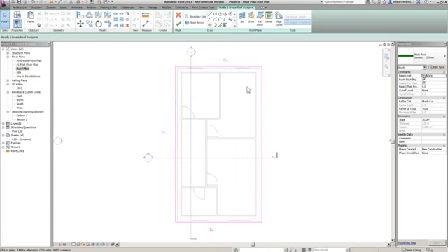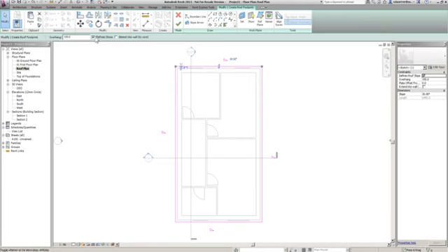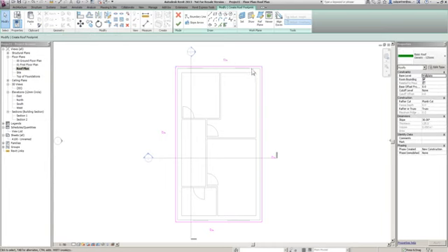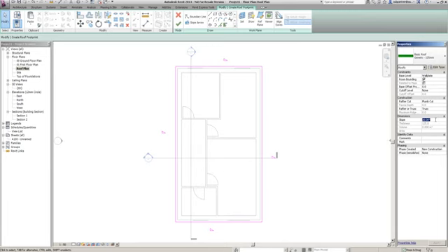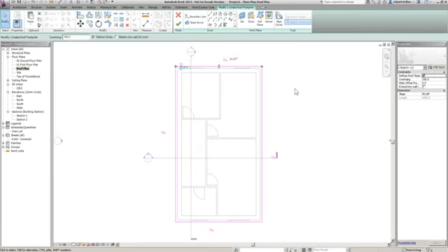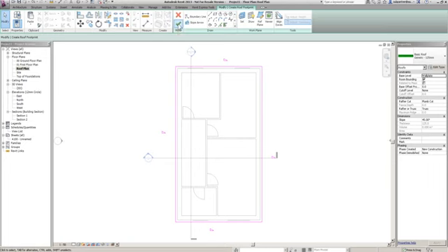Now just note, all of these lines have this little triangle next to them. That means there is a slope defined to it. If I highlight it, you can see that box there is ticked. Also, with it highlighted, you can see what the overhang is, and you can also see what the pitch is to that. It's called slope in this, but we'll know it as pitch. Okay. Now, if I select that, I can change each pitch individually by clicking there, or with nothing selected, I can just change all of the pitches. Let's just say 45 degrees or something like that, and then when I click back on it, you see that's 45 degrees. I'm now just going to finish it.